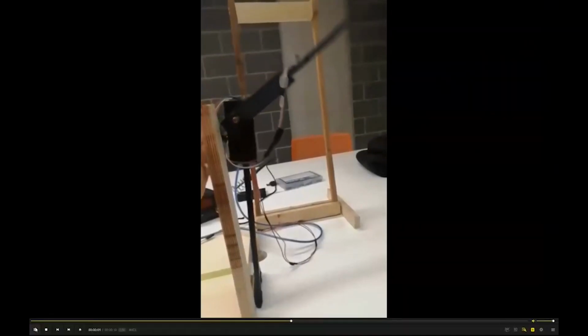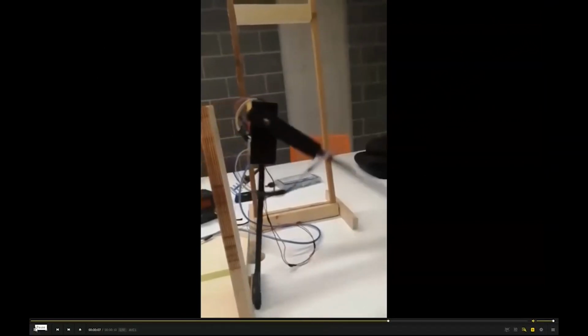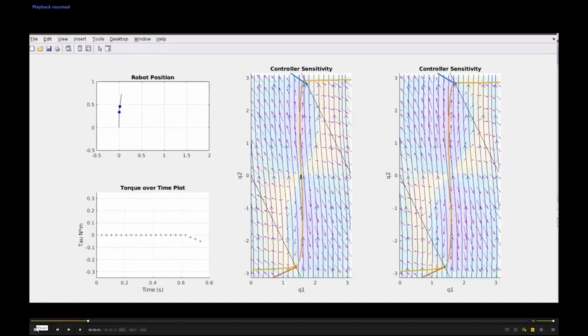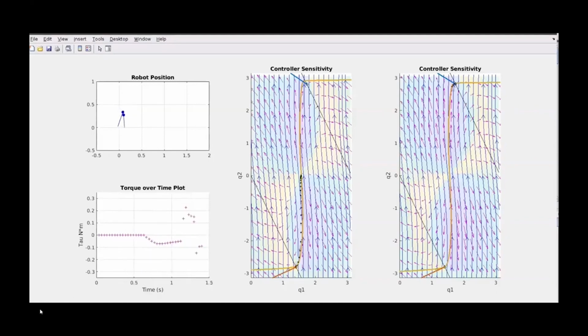As you notice, when it's completed its bounce, there's a slight deformation of the leg. This deformation created the bounce and made it very difficult to walk. In order to address the bounce and slipping issue, an additional feature we have with the curves is to reduce the velocity of the impact with the ground.